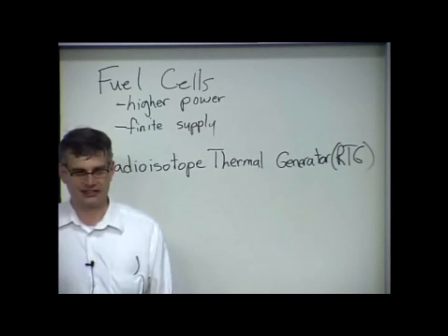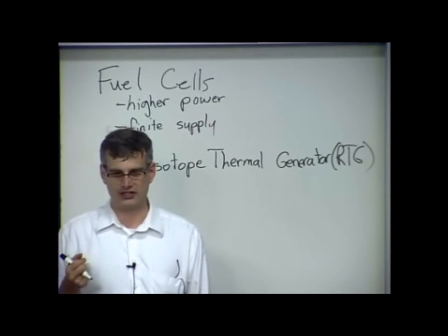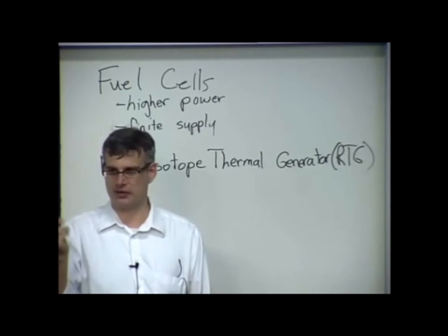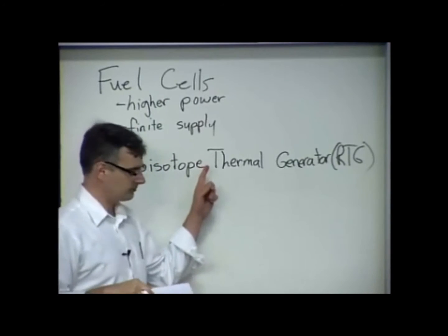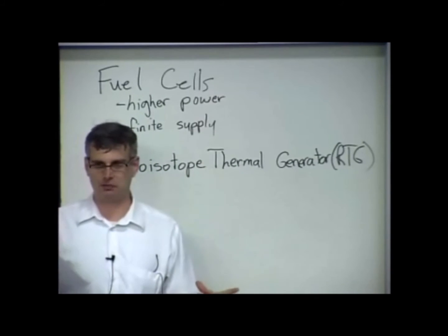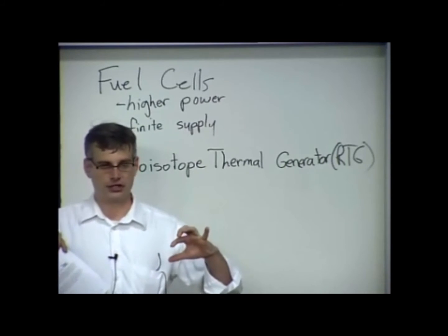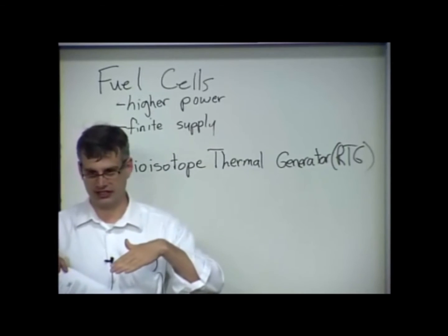This is very much like the little hockey pucks on steroids, the hockey pucks that you use to warm batteries. Nobody minds if you put these encapsulated hockey pucks that stay warm on a battery in a spacecraft. However, what you do is you make a much bigger pile of radioactive material. You wire it with a bunch of thermocouples, and you convert the thermal energy into electricity.